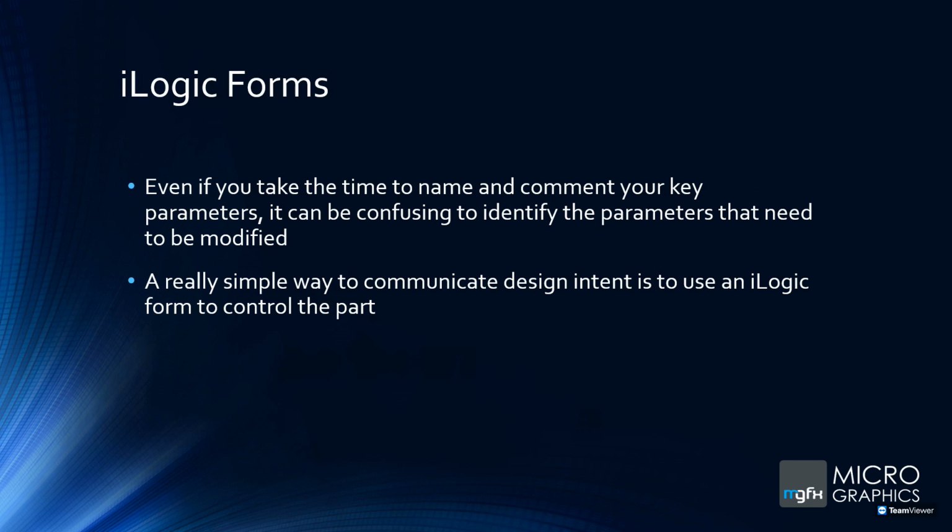Okay, so some of you might have heard of iLogic, some of you might not have. It is programming, or if-then statements. There's a little bit of VB involved, but you don't have to use that to help with your design. We've got something in there called iLogic forms. This helps when it gets to identifying the key parameters, so that you can very quickly and easily change them instead of having to open up the parameters dialog box and scroll through your 5,000 or 1,000, whatever, parameters that you've renamed to get to the correct one.